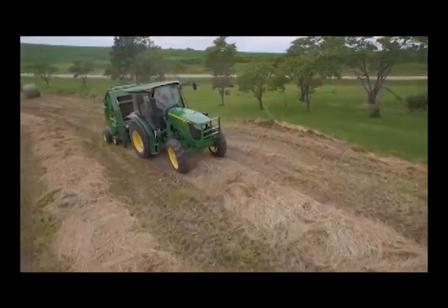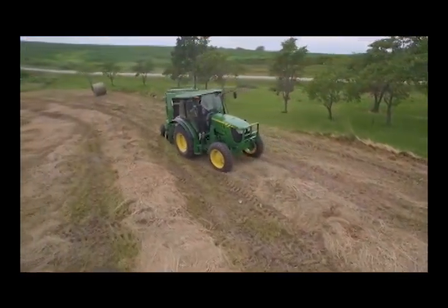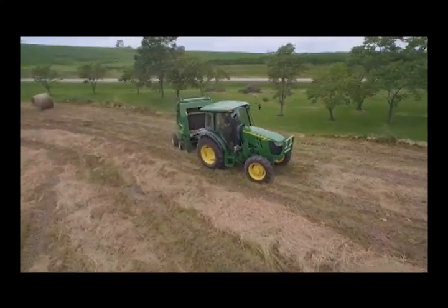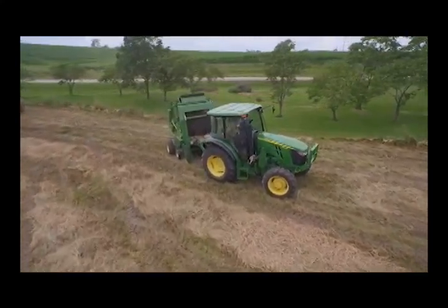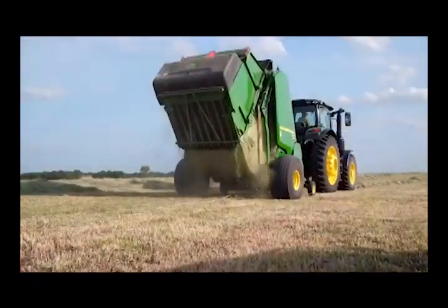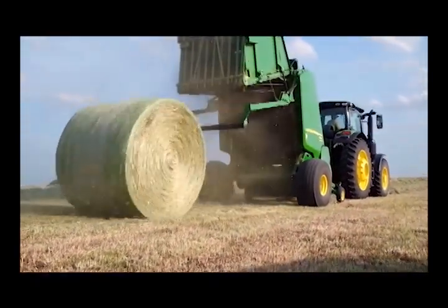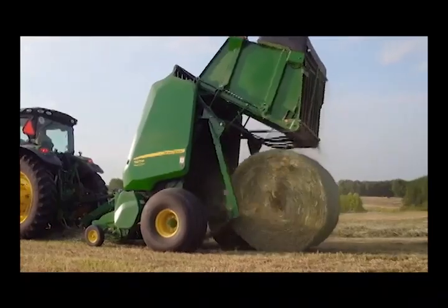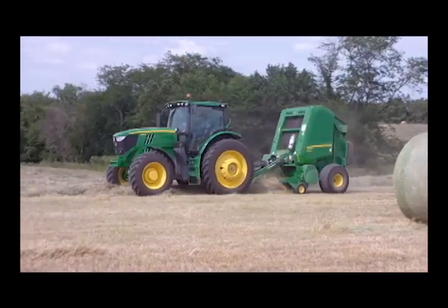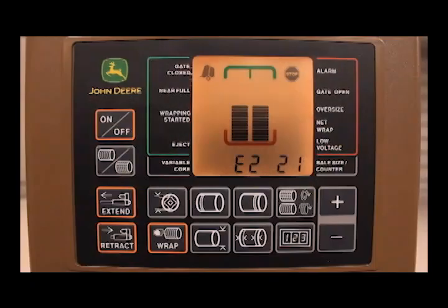If your baler is not equipped with bale ramps, a bale push bar, or an accumulator, you must back up and then eject the bale using the hydraulic control lever for the gate lift. If the baler is equipped with a bale ramp, push bar, or an accumulator, in most conditions you will not need to back up to eject the bale or drive forward to close the gate.